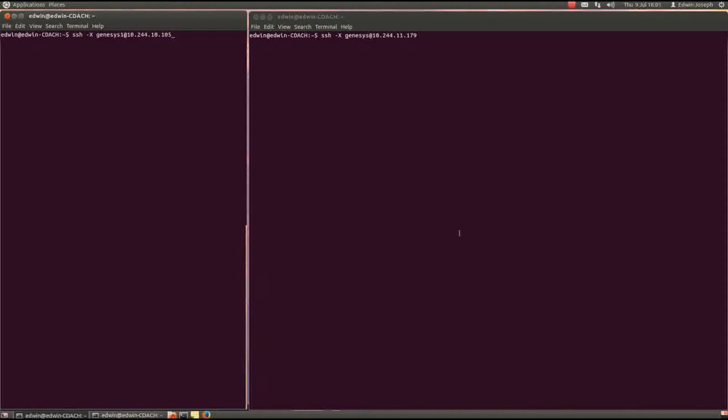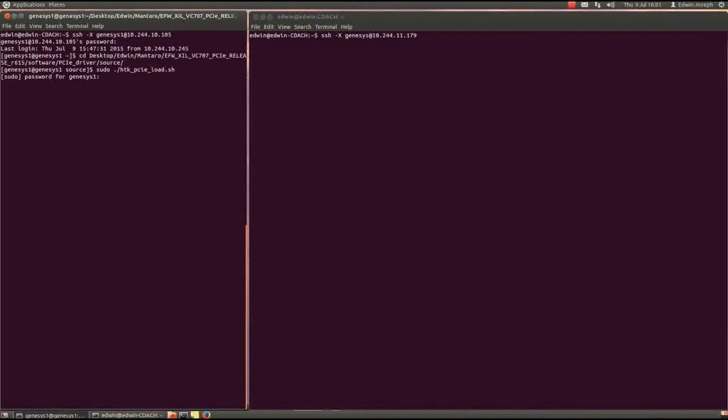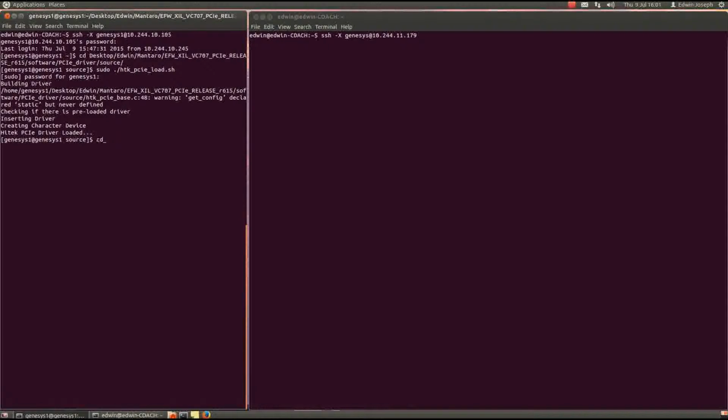After the server system with the FPGA board reboots, we load the driver for the PCI configurations. Currently, we are using a node-lock MAC and DMA, which is time limited by the vendor to 10 to 15 minutes.